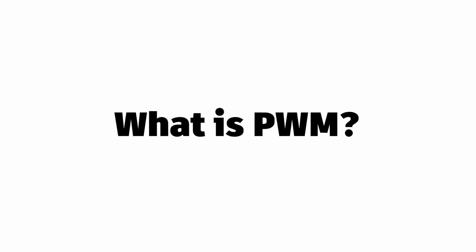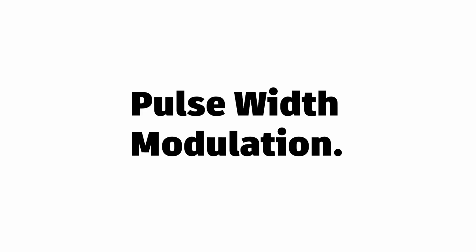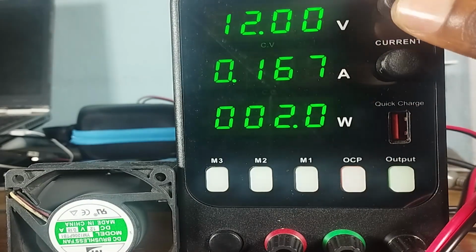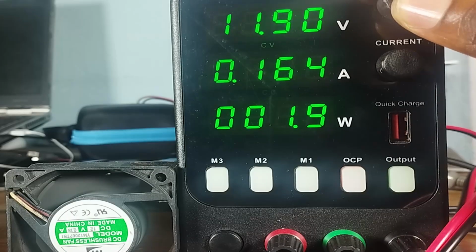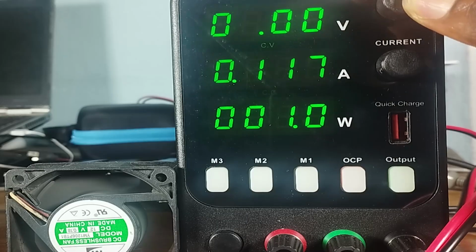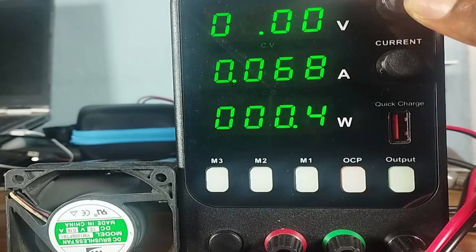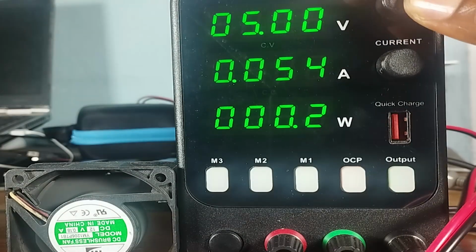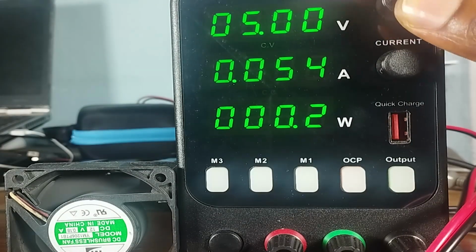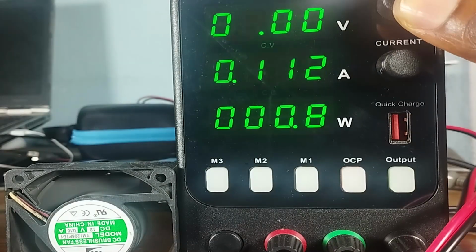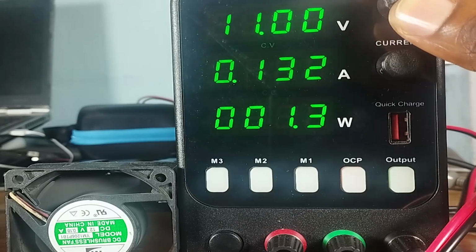What is PWM? PWM stands for pulse width modulation. Normally, when we want to control the amount of power sent to a load, we reduce or increase the voltage sent. But doing this creates opportunity for heat loss, and when it's something we have to control from a microcontroller, it becomes impossible. Since the microcontroller can't just change the voltage level you can get from its pin just like that. If it has to do this, it does it through pulse width modulation, and this it does by switching